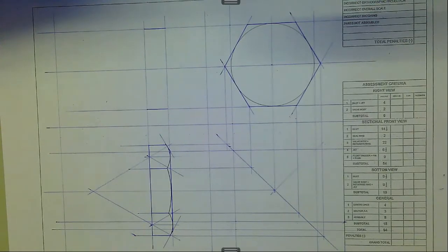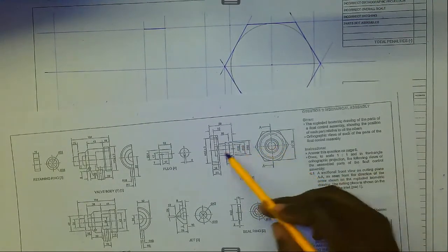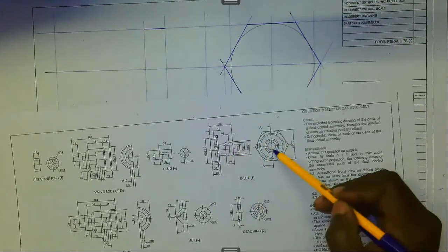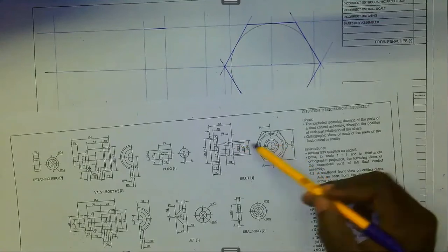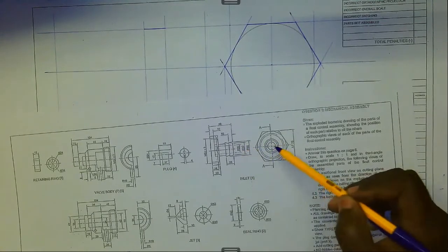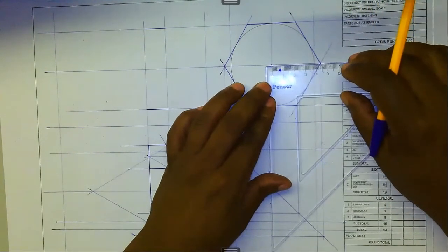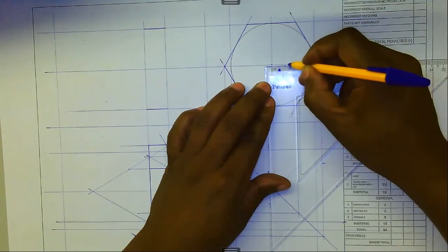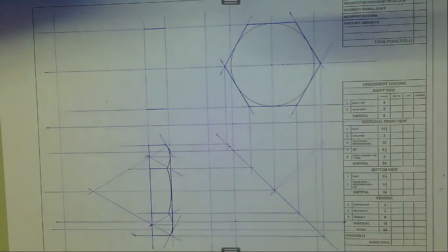Right. The next detail that we want. If you look at this, there is that detail which can be defined on the front view in terms of the right view. So there's a front view, there's the right view. So that detail, we've got diameter 36, which is the tip end, then diameter 30, which is for this one, and then diameter 20. Right, so let's measure those diameters. 36, that's radius 18. Right, then radius 15 and radius 10. This detail will be seen right in terms of the front view.